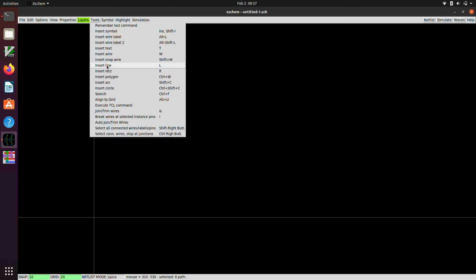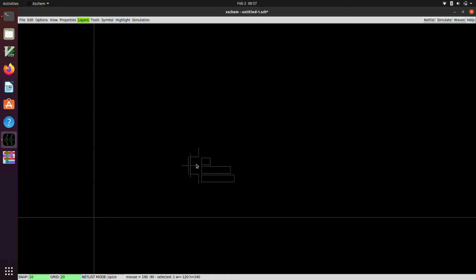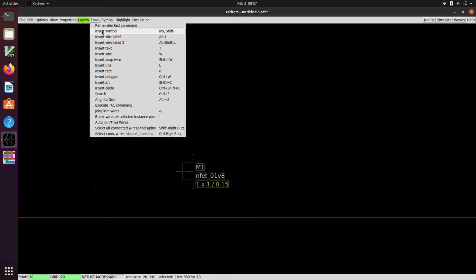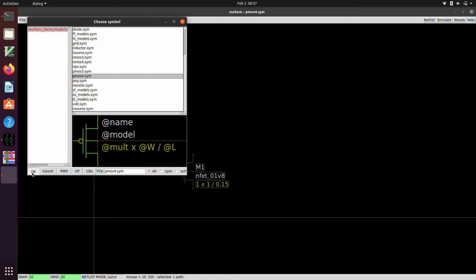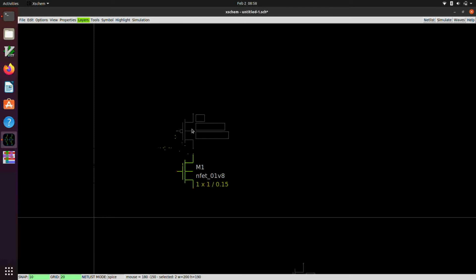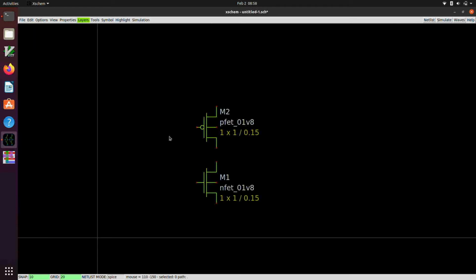It's going to look a little different than the inverter that we made in the last tutorial. We're going to use a 4-terminal NMOS and a 4-terminal PMOS for this particular inverter. Oops, and that's what happens if you don't deselect the thing that you had previously selected. It gets picked up and moved around as you instance the new symbol.